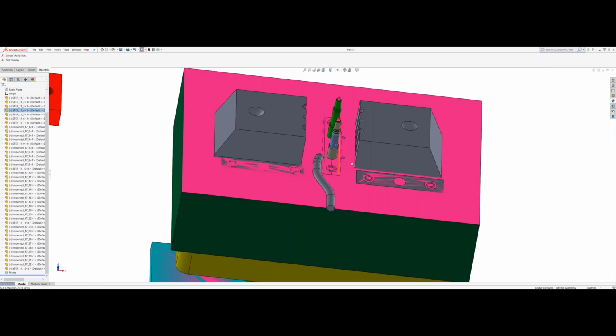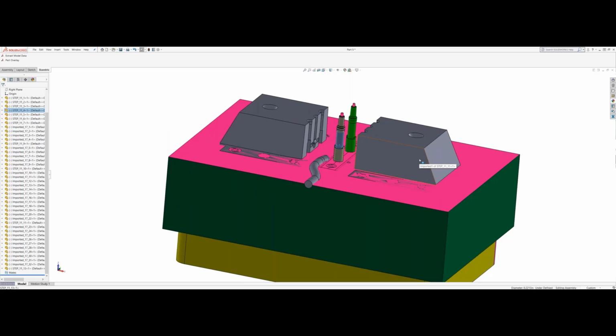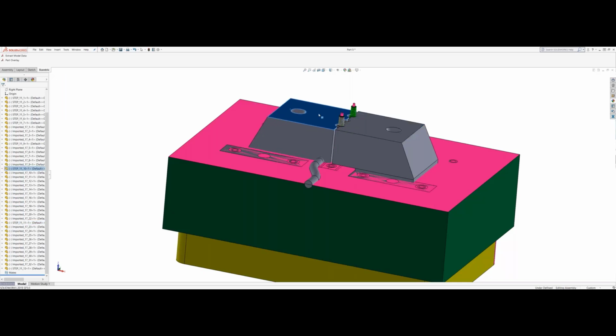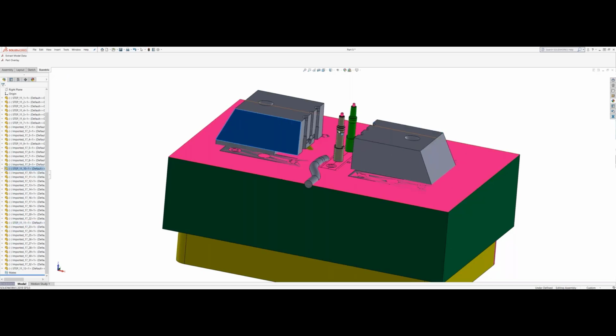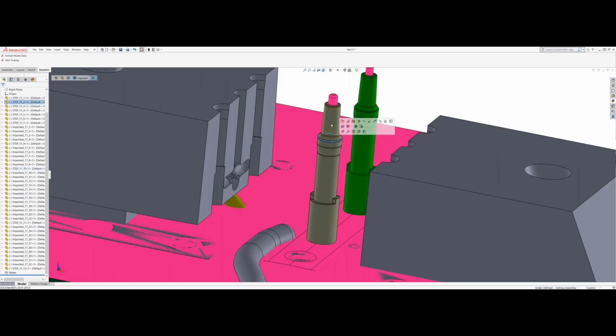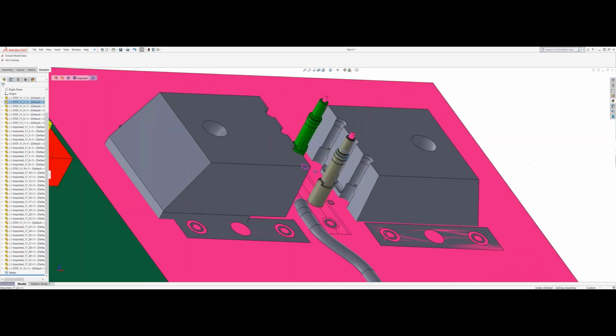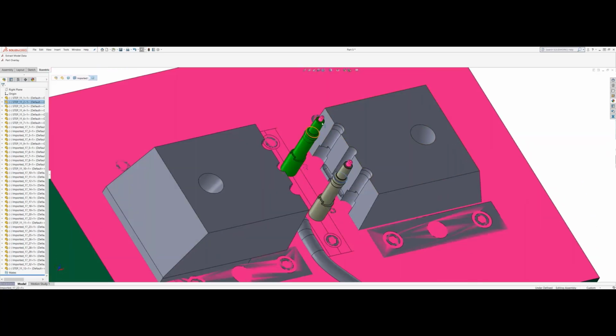This is an example of an automated tool. Parts fall out, these cycle back in, shut off on each other, and just repeat. Our main parting line is roughly right here on the part. This would be embedded into the cavity side of the tool. These pins are a little bit longer, so they lock into the cavity side so you don't get any sway during molding. Typically on round parts like this, you want gates on each side to keep these pins straight and even.